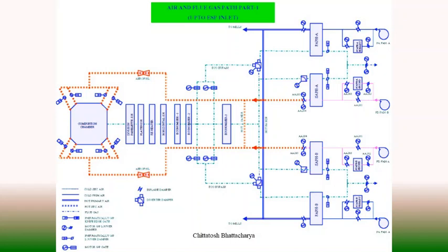These fans are there. Beside that, for flame scanning, we have flame scanners within the vicinity of the boiler furnace. These flame scanners are scanning the flames within the furnace continuously, and remotely the presence of flame is observed from the control room. But these flame scanners cannot work beyond a temperature of 90 degrees centigrade, so naturally they need cooling air continuously. So scanner air fans are provided to maintain the cooling of flame scanners. There are also AC and DC scanner air fans.